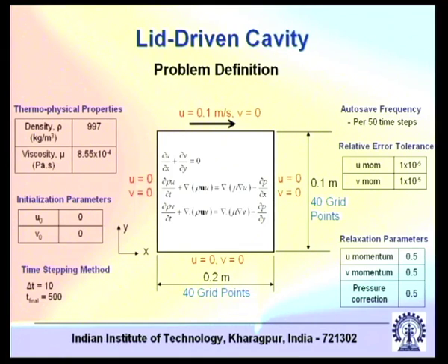Say you have a boundary layer flow. When you have a boundary layer flow, you need to capture the strong gradients of velocity and temperature, depending on what type of boundary layer it is, within the boundary layer. To do that you require a large number of grid points within the boundary layer, at least a substantial number. If your gridding is such that you do not have any grid point within the boundary layer, say one is at the boundary and the next one is outside the boundary layer, then you are not able to capture the physics within the boundary layer.